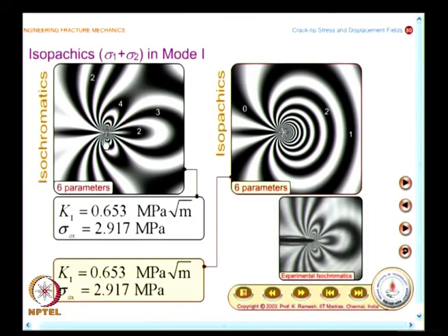You do not find a great change in the geometry. See, we have been discussing for the crack problem, we wanted tau xy to be 0 on the crack axis. Westergaard solution turned out a surprise that tau maximum is also 0, which is incidental, we did not want it, whereas the experiment shows there is a variation of maximum shear stress along the crack axis, which is beautifully captured when you go for a 6 term solution.